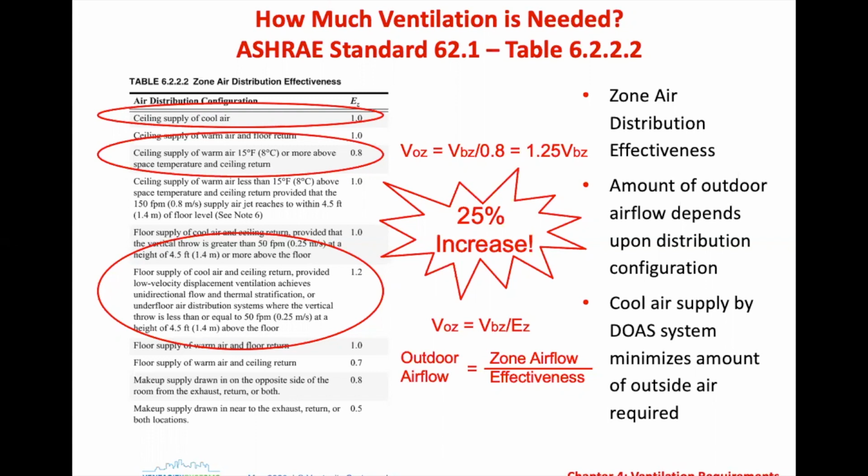What's really important is when you look at very high efficiency heat recovery ventilation, that means that you're bringing air into the room from your ventilation system very close to the same temperature that's in the room. So that does mean that your direct ventilation is going to dilute, it's going to disperse into the room very readily. And in my days with Zender, we had done some theatrical smoke tests where, introducing air in just a small vent in a corner of a room, if that air was within 5 degrees Fahrenheit of the room temperature, that smoke would tend to diffuse into the room.